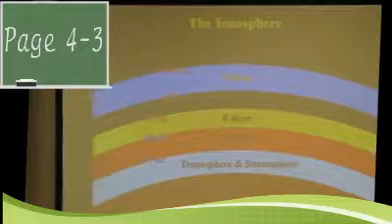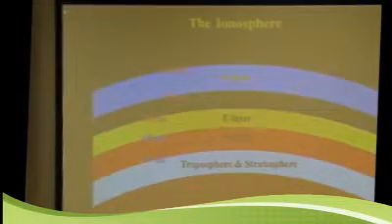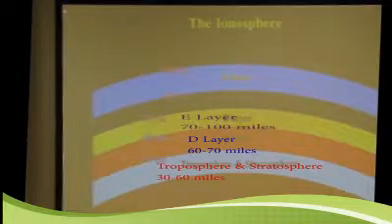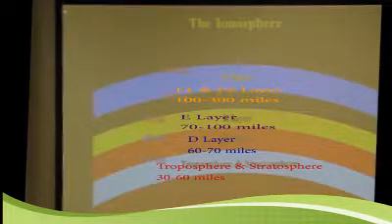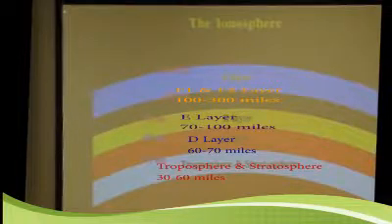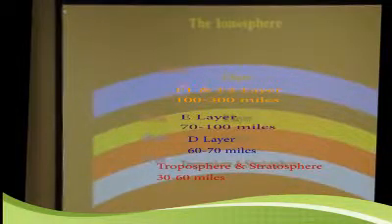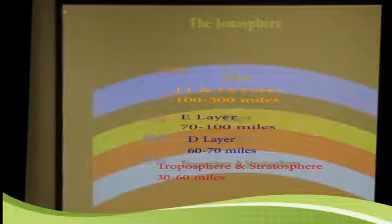So here we have the ionosphere. You've got the troposphere or stratosphere from 30 to about 60 miles, then what's called the D layer at 60 to 70, the E layer, and in the 100 mile to 300 mile range, you've got the F layer. First of all, these numbers are not hard. That's approximately where they are, and they shift. This F layer can shift lower, can go higher. It bounces all around. This is not a hard piece of material out there. This is a radio wave ionization layer, and its ability to reflect, where it tends to reflect, and so on, changes all the time. That's what makes things interesting. It makes it tough if I absolutely have to talk to somebody in Nigeria this afternoon.